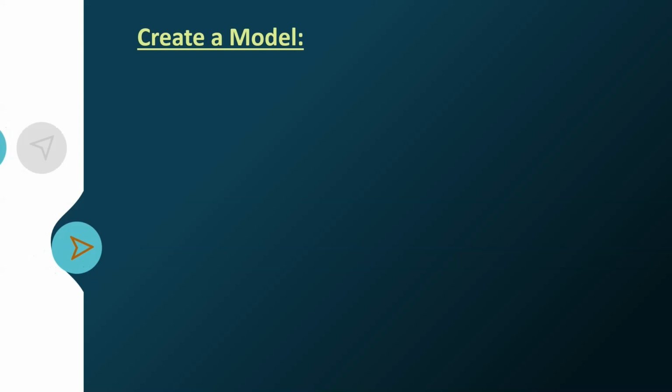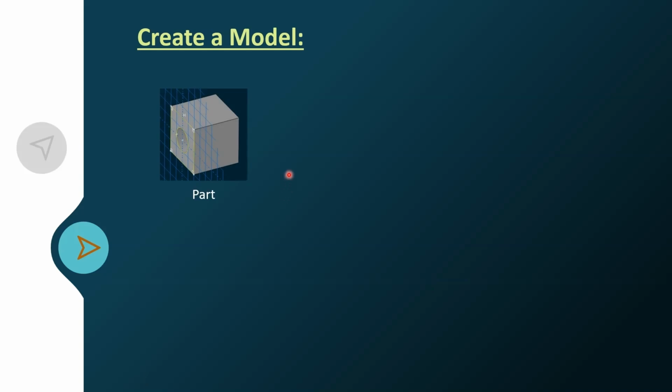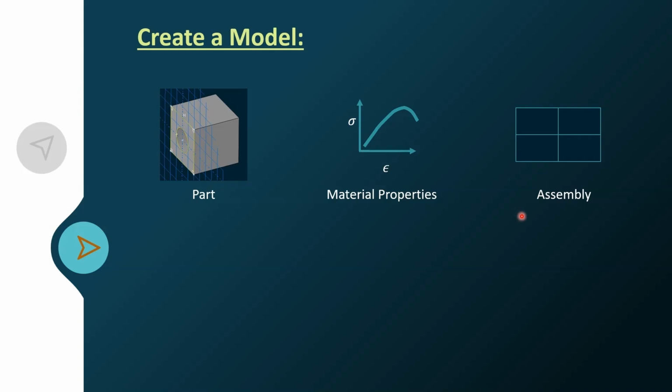So what things do we have to consider while doing this? There are multiple steps involved in this pre-processing, that is, when we want to build the model. So one is creating a part, which is nothing but a blueprint. I may have discussed this already. There are multiple ways you can create a part. These are the individual components you can consider in the assembly. Then these parts need to be assigned certain kinds of properties which are required to simulate particular behavior. Then we have to assemble these parts, but as our model is very simple, we don't need to do extensive assembling here. But that is how the Abaqus convention is, so we have to do the assembly.